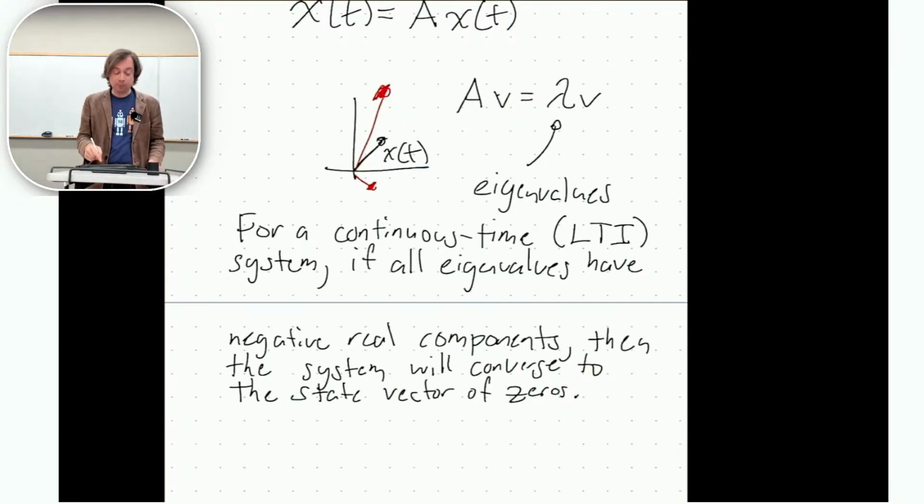And sure enough, if you compute the eigenvalues for that spring mass damper, if you have a physics-obeying damper that takes energy out of the system, guess what? It's going to be stable, and those eigenvalues will show it to you. But if you have a magic damper that has a negative damping coefficient, meaning it adds energy, that eigenvalue is going to be positive, and it's going to shoot off. That's pretty valuable, right? To know if your system is going to fall down.